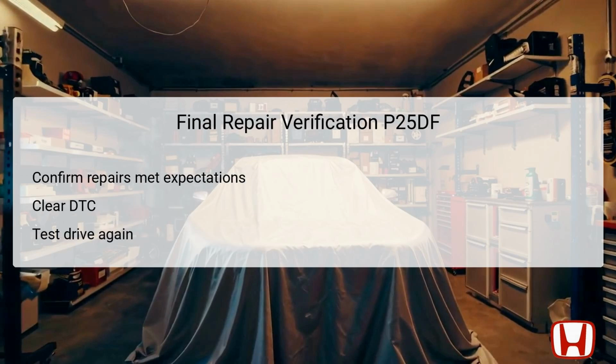Once repairs have been completed based on previous troubleshooting steps, it's essential to verify that the work done has resolved the issue. Start by confirming that all repairs performed met the expected standards, including inspecting the VTC oil passages, oil control solenoids, and oil pressure levels.